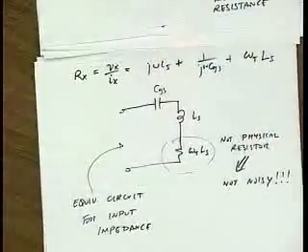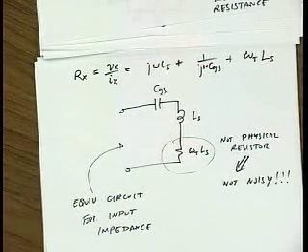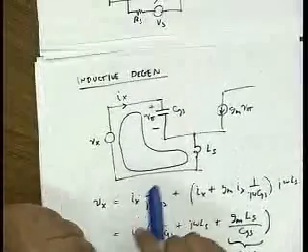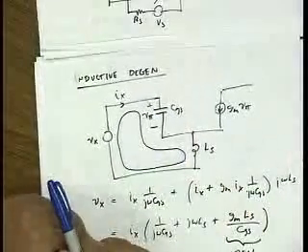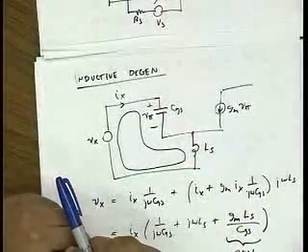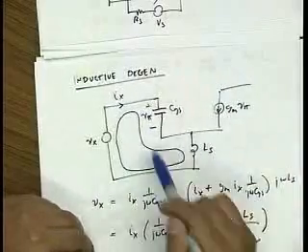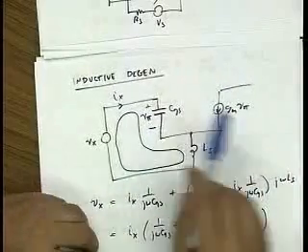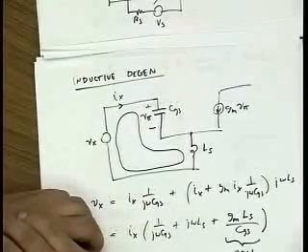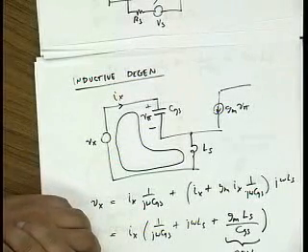Yes. Is this for both BJTs and MOS, or is this? Yeah, that's a great question. If you look at this equivalent circuit, it looks more or less the same for BJT and NMOS, right? Or PMOS for that matter. So this is really kind of a universal idea, and it's used for both bipolars and for MOS amplifiers.